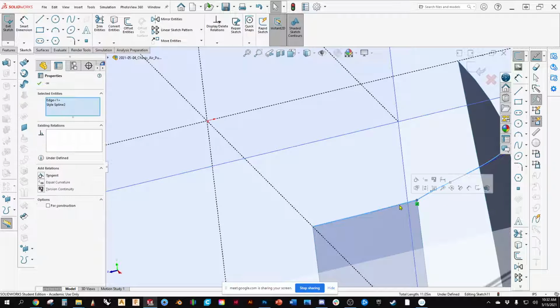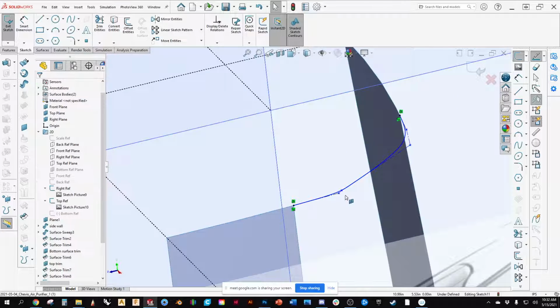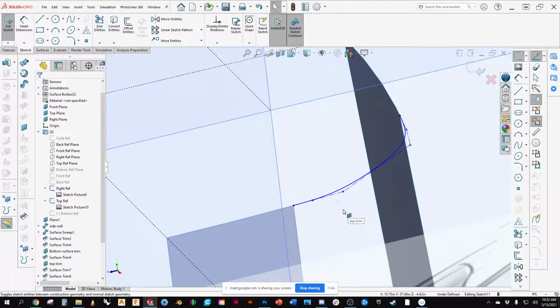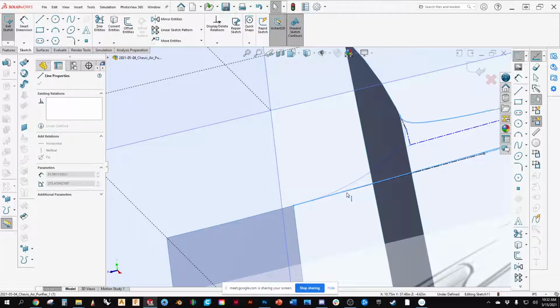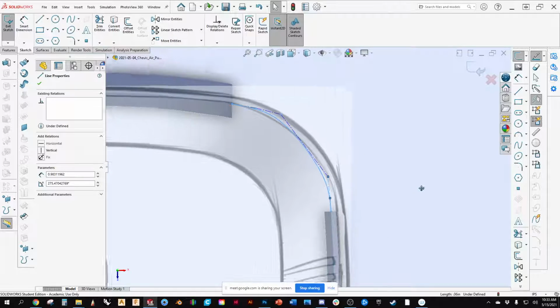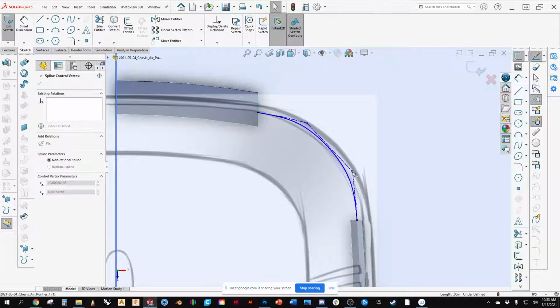Same thing. One of the problems that I keep getting when I try this approach, because this is what I've been doing in my spare time, is whenever I try to get curvature continuous on both sides of it, it keeps telling me that it's overdefined. Especially, for example, if I have it pierced on both sides and then get curvature continuous, it tells me it's overdefined. And if I delete the pierce, it's like, okay, this is fine. It's pierced on this part, but it's not pierced here. It's still fine. It's very confusing to me.